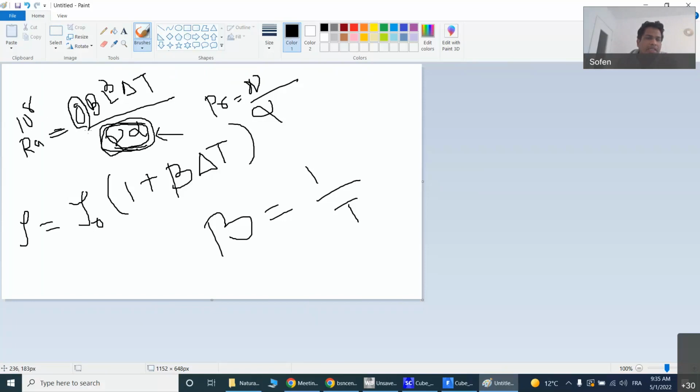This gravity is again another constant, right? Then this L cubed, you have already chosen the dimension of the cavity in the temperature gradient direction. L is the dimension, so it's around 0.5. This is also fixed. The only parameters available to you to make changes are beta and delta T, meaning how much compressibility effect you are providing and how much temperature difference you are maintaining.